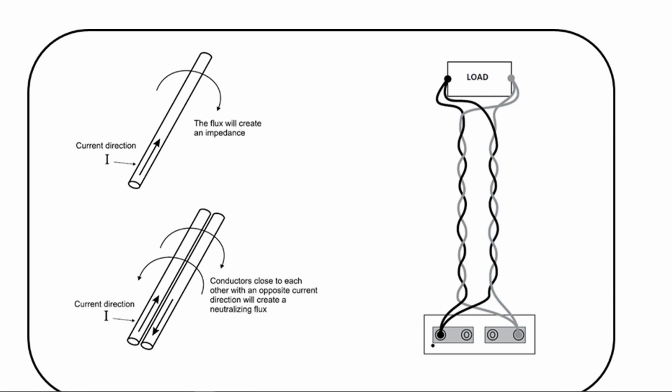When, and of course, a really easy to follow recommendation, right? But also really easy to make it incorrect. As you can see, and just for the clarity, we use two colors here. If you see on this current box that we have at the bottom, we have the polarity mark on the left with the black dot. And those two conductors that go out from that side of my current box are black. On the other side, I have gray cables.